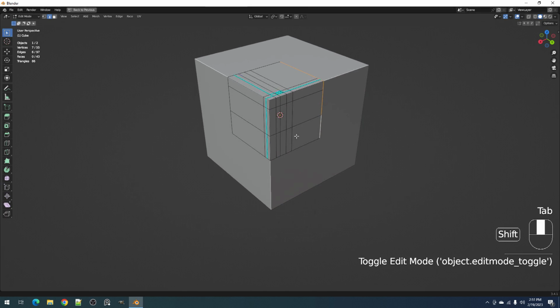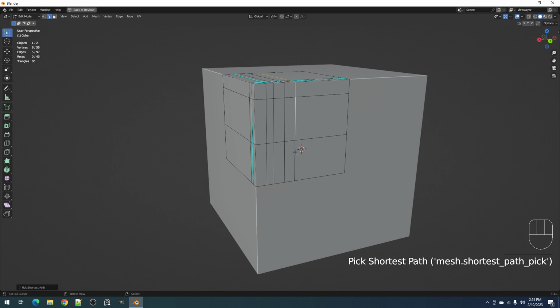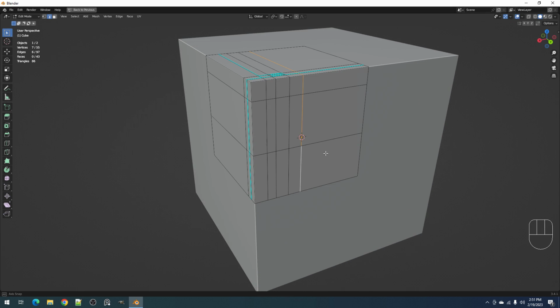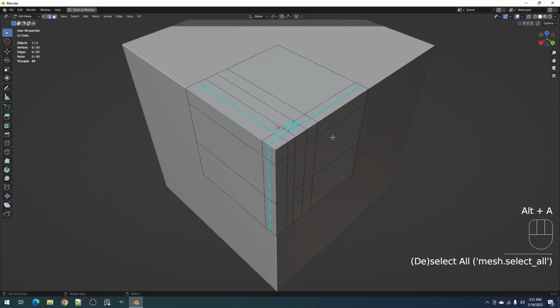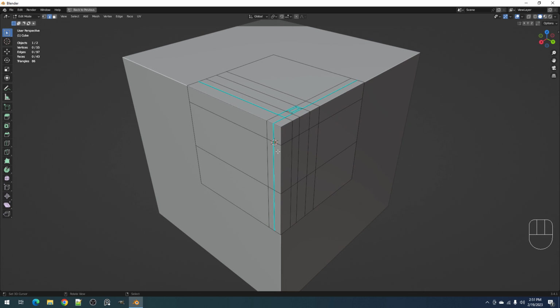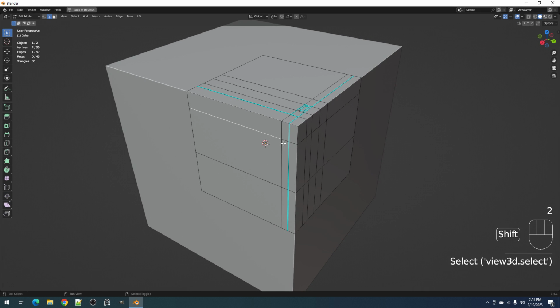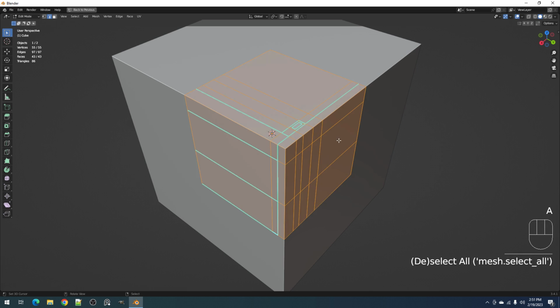Like the ones we did here, where the lines ended up here, it should be continuous, and this edge should also be marked as sharp. Okay, so we'll just continue designing this one. So the add-on respects, or takes into account, the mirror modifier.